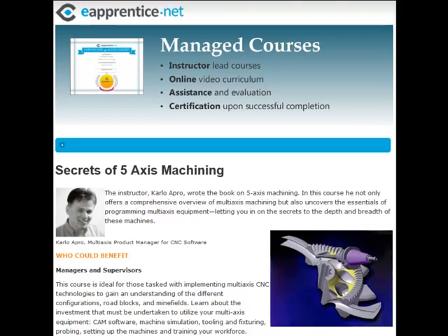So I've got a question coming in from Justin. Carlo, do you have a library of machines that you use for the visual verification, or do we send you sizes, etc.? Just want to make sure it would be accurate. There are 17 machines installed with Mastercam since X5, and they are designed to be templates to build your own machines.